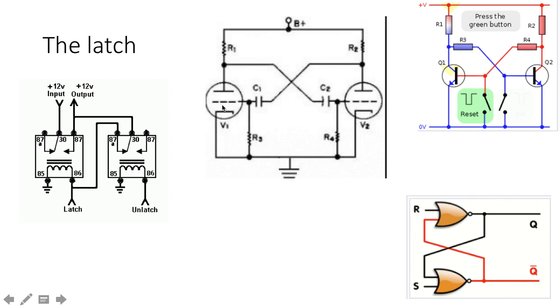This is what you call a triode. It has three elements: a cathode, a grid, and an anode. The grid serves as a gate of power that goes from the cathode to the anode. When the cathode is replaced by simply a filament, and then you have nothing more than a filament and an anode, the filament can be used as what they call a hot cathode, and that's a Fleming valve, or a diode, which was originally used by Sir Ambrose Fleming when he was acting as a consultant for Samuel Morse to improve the sensitivity of the transatlantic telegraph.